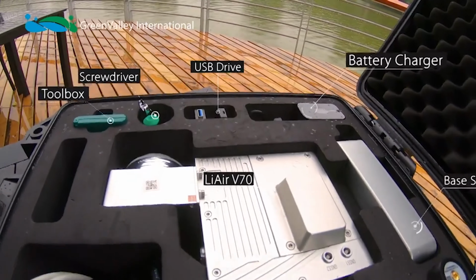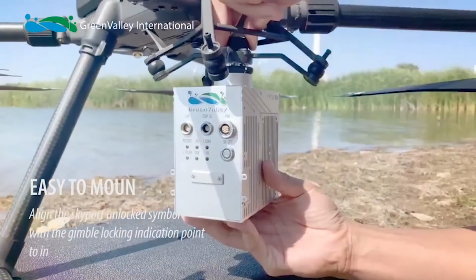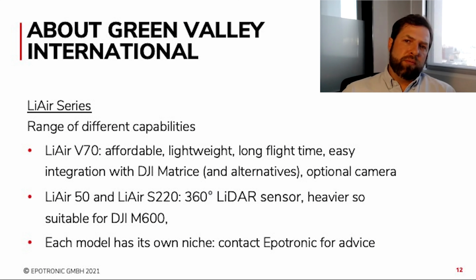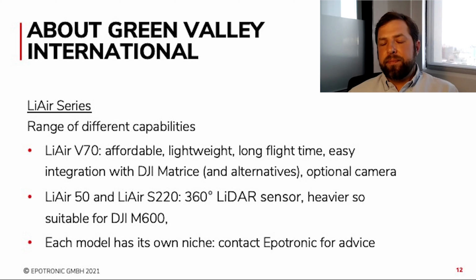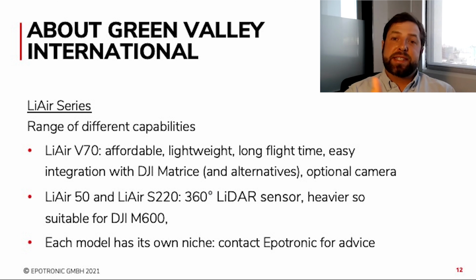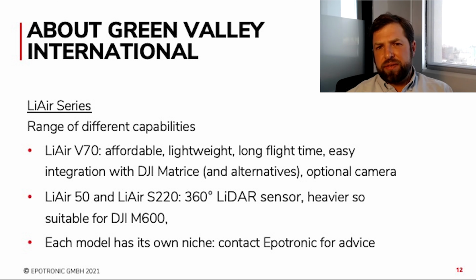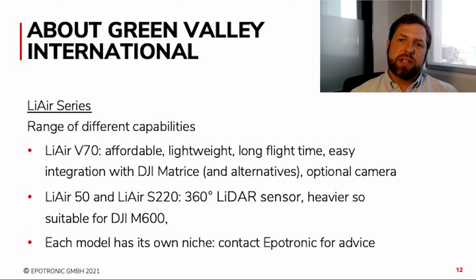It's also adapted for easy integration into the DJI Matrice series through the Skyport. But it's also flexible enough to go onto a non-DJI drone, pull power from an external source, and we have all the hardware necessary to do that as well. We also have the service capabilities to work with you if you need a custom calibration file developed for the way that you integrate something like the LiDAR V into your drone so that you can then process that data using our LiGeo reference software. And you can also choose the option of adding a camera on this. And this is actually something that's quite popular because you can use that pose data collected from the LiDAR V to geotag your photos and then push it through a photogrammetric workflow as well. So it can be done in our LiMapper software.